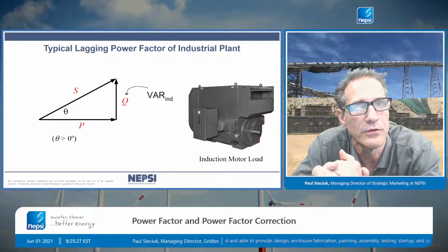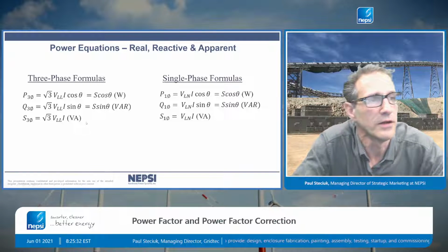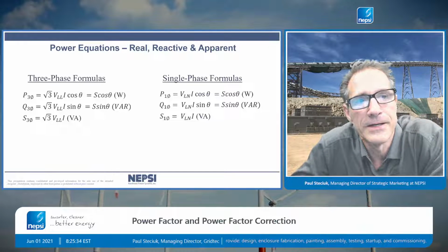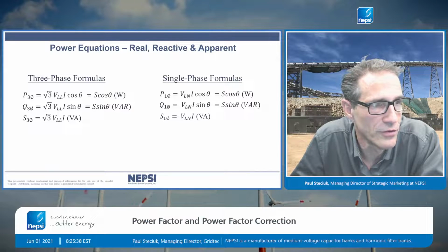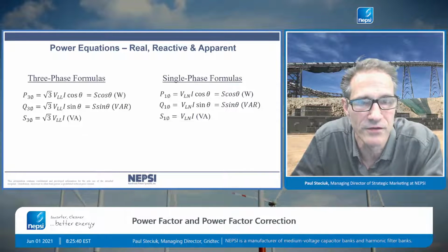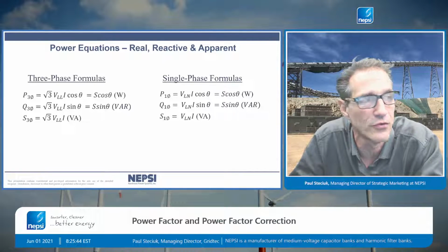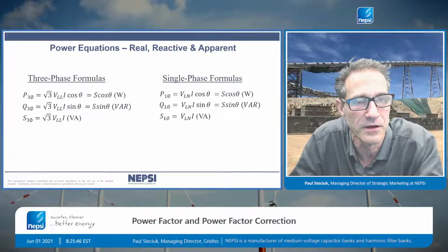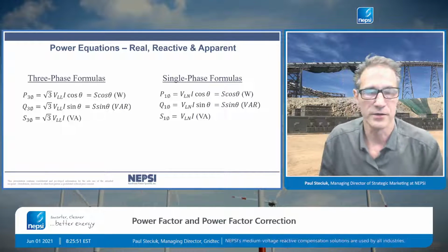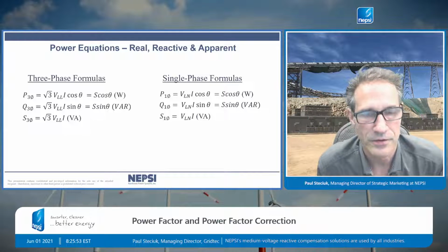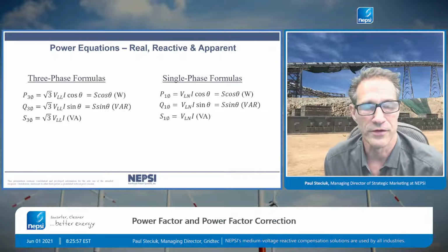So typical lagging power factor, this is the motor. Let's move on. So the three-phase formulas. These are the formulas that we most often use, and I will tell you that three-phase formulas, I almost always work with three-phase power. Very seldom do I work with the single-phase formulas. By and large, medium voltage systems, the systems I'm working with are three phases, and we're working with three-phase loads.